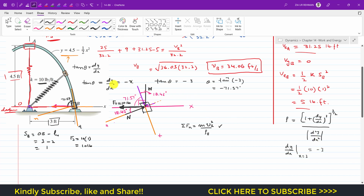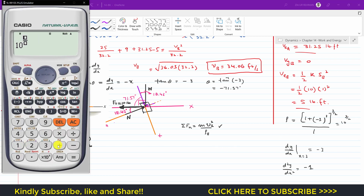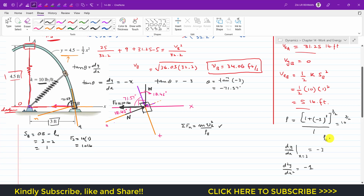And if we take the second derivative of this, dy by dx is minus x, so d square y by dx square will be equal to minus 1. Now if we put these values in this equation, dy by dx is minus 3, and the absolute value of d square y by dx square, minus 1, is 1. So 1 plus 9 is 10, so 10 to the power 3 by 2 divided by 1 will give us the radius of curvature, that is 31.62. So the radius of curvature at B is 31.62 feet.